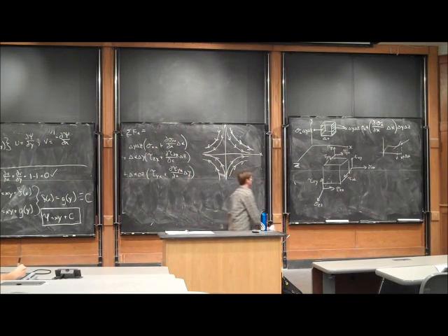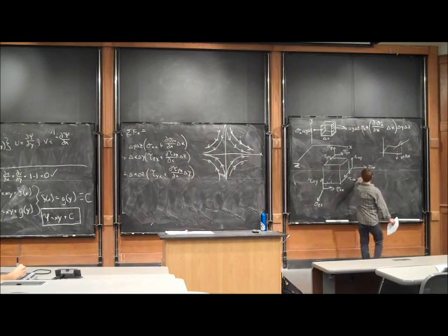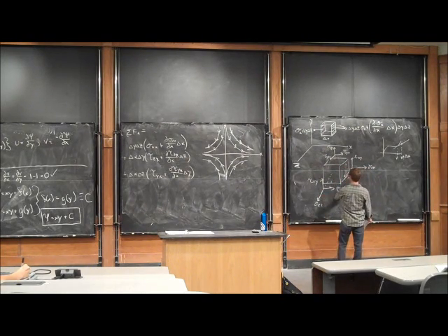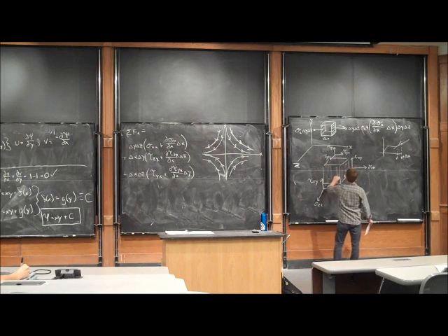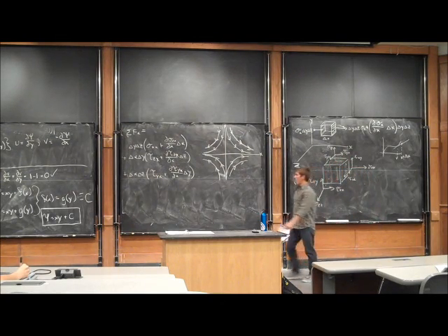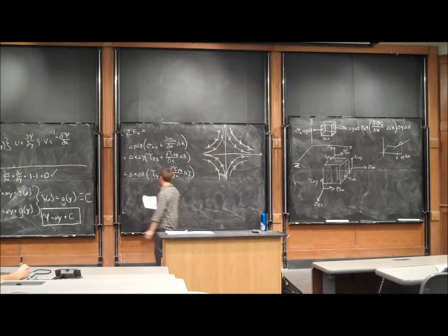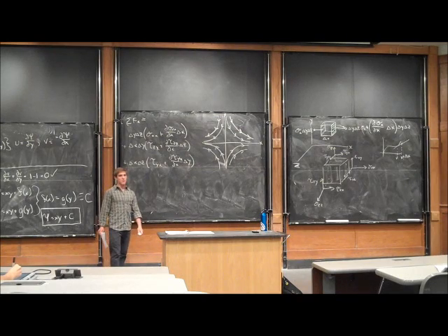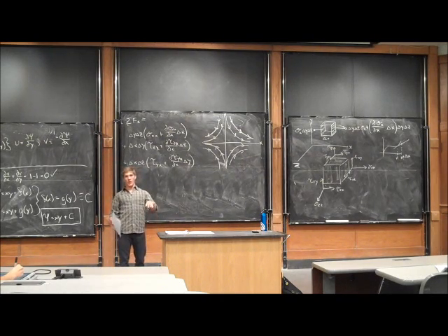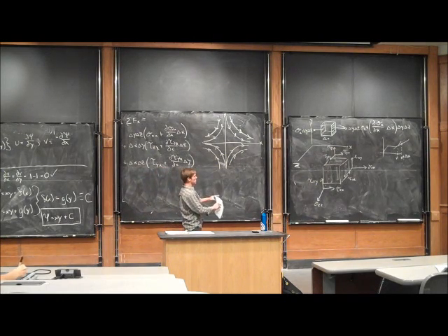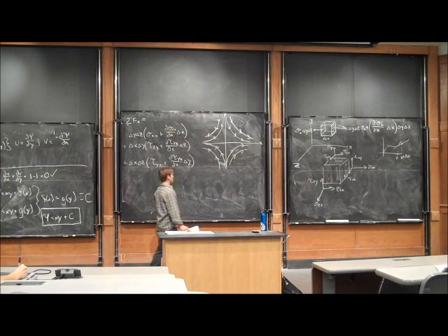So this is just nothing more than this stress acting over this area, this stress acting over this area, and this stress acting over this area. Those are just forces acting on the fluid element. We can also have what are referred to as body forces, something like gravity or an electric field. If we picked our coordinate system such that gravity has a component in the x direction, we also need to account for that.